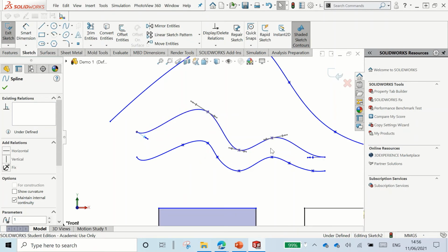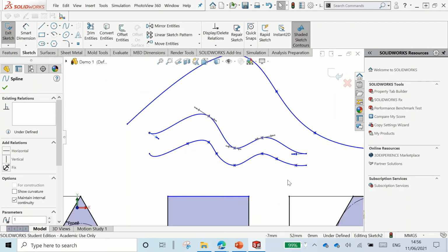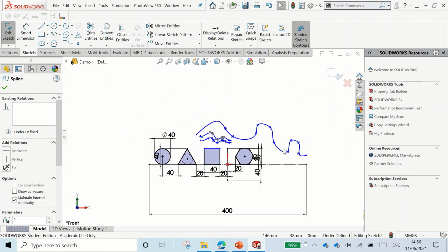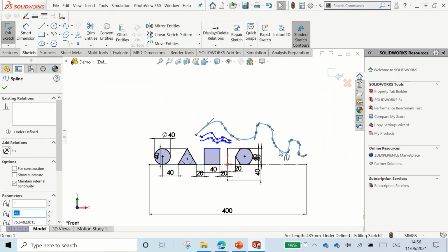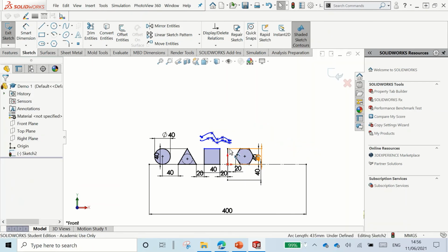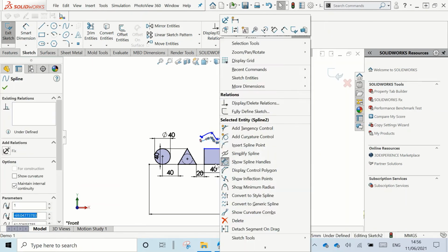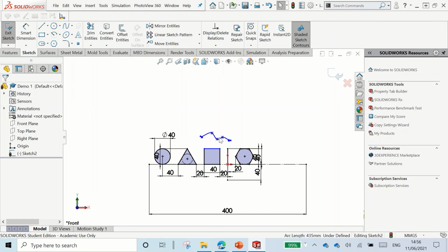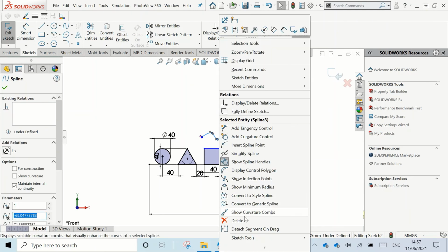But you'll find when I go to extrude that curve, that's a much better surface, much cleaner curve. There's less dimples and it looks far better. So going back to what we were doing. So I can delete them. I can just right click them and delete if you're ever unhappy with anything. Right click, delete, and right click, delete.